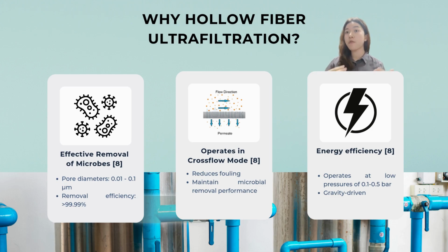It implements cross-flow filtration mode, which can reduce membrane fouling and extend the lifespan of the membranes. As the operation occurs at a low pressure of 0.1 to 0.5 bars, it requires little energy, making it energy efficient. It is gravity-driven, making it suitable for rural areas.